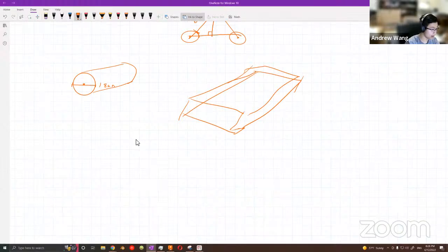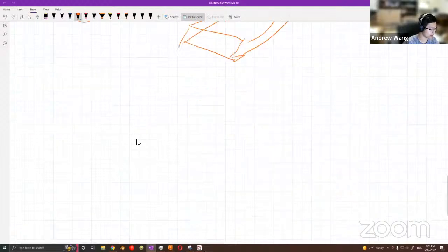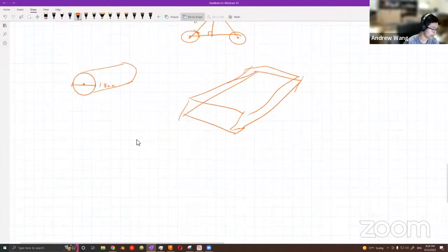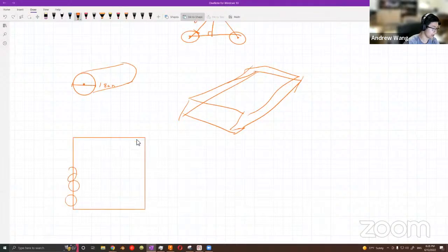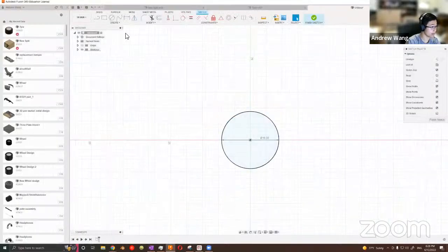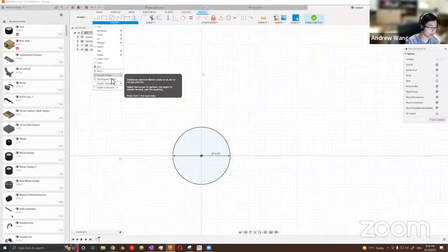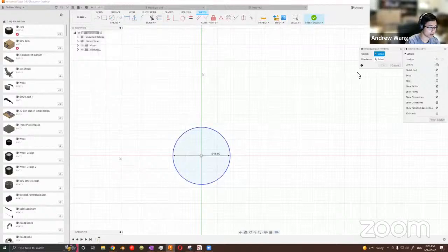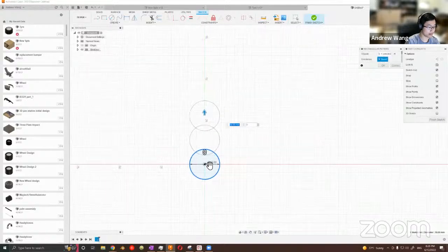If your first thought is to build a pack like a rectangle, like this, with cells that go up, up, up, and keep on going up like that, let's design that in Fusion 360. So I create a rectangular pattern, using the objects and directions option, and I can go in two directions.